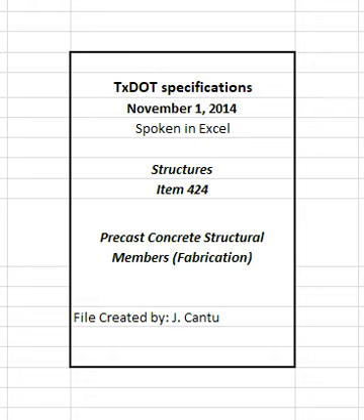4.2.8 Detentioning. Release the tension in the strands after concrete strength requirements are met using a sequence to minimize premature wire breakage or shock and damage to the concrete members. Release strands by multiple strand detentioning or single strand flame detentioning. Ensure strands are not released individually with single strand jacks. Flame release each strand simultaneously at both ends of the casting bed, using a symmetrical sequence prepared by a licensed professional engineer if strands are released individually.